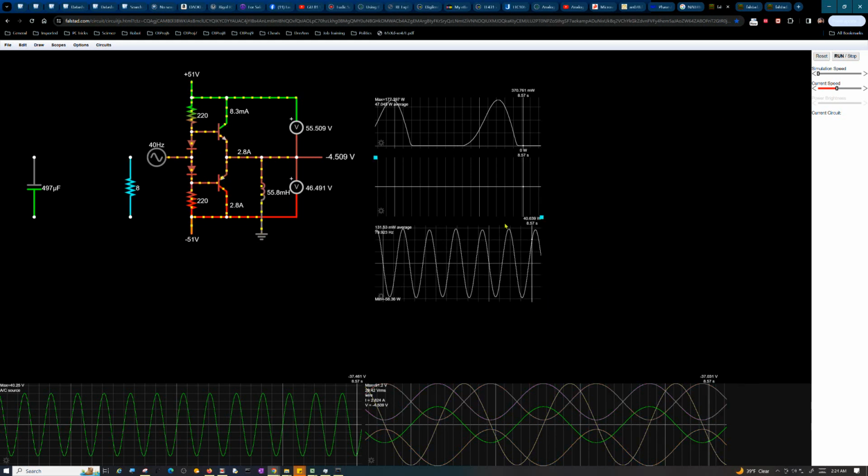Okay, but so yeah, guess what? You can, but you can see the power is above and below the zero line, right? So that means power is being gathered, energy is being stored, but then it's later being released and going the other direction. So there's no net power like you see over here, because you should see all the power above the zero line, or all of it below the zero line, as the case might be if you got your stuff backwards.